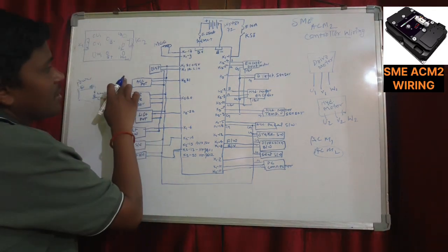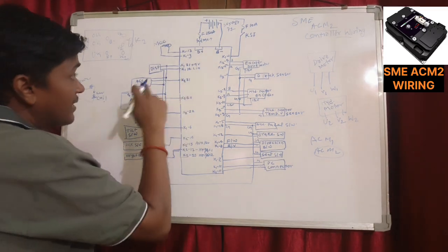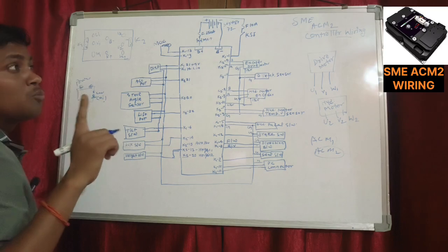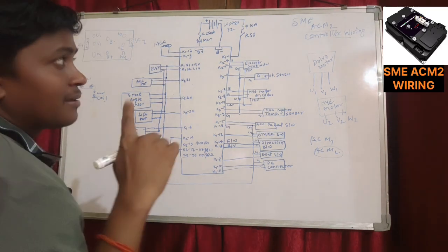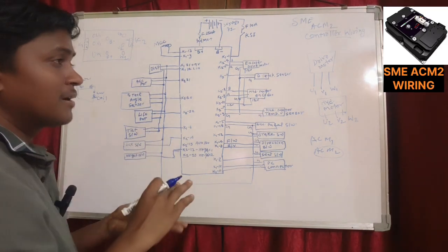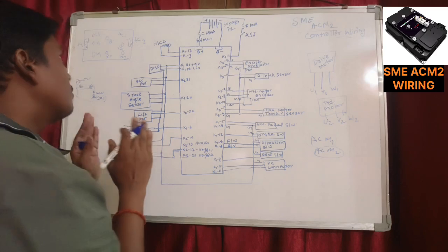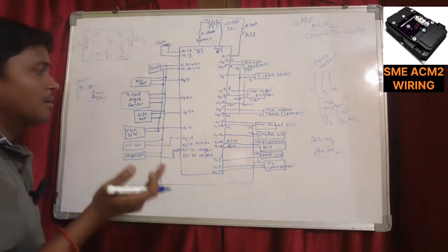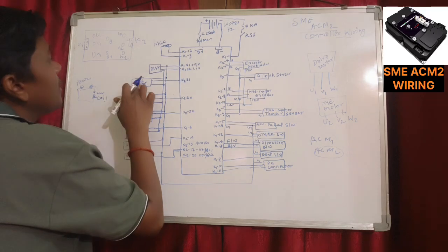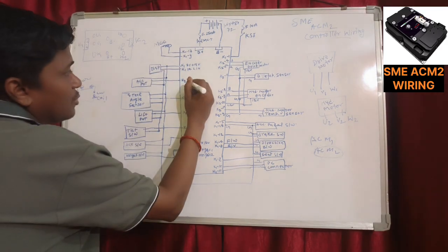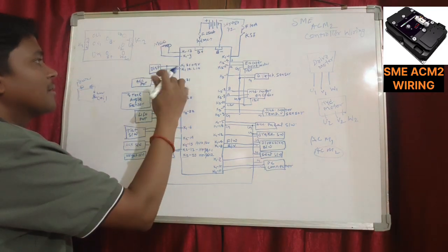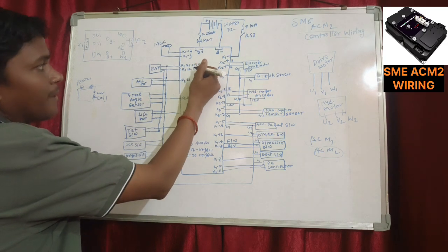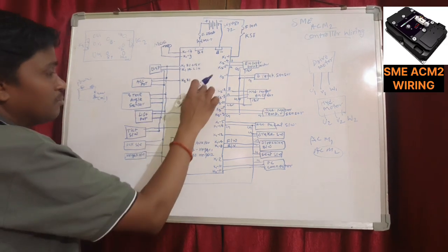The accelerator port point, having which accelerator port? This controller will operate two motors, one drive motor and another hydraulic motor, or you can control the drive motor alone, whichever you require. Then the accelerator port will be connected to K221 and another 12 volt and ground from the controller.